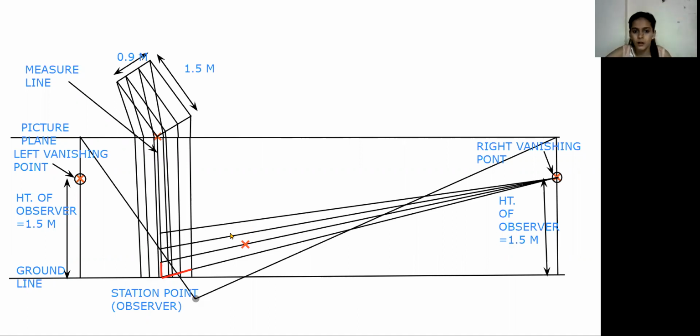Okay, so on this cross mark inclined line, we need to draw a tread. Between which lines? Between this point vertical line. Okay, so we are just going to connect it. So tread. After tread, again riser. So on this vertical line, a riser.